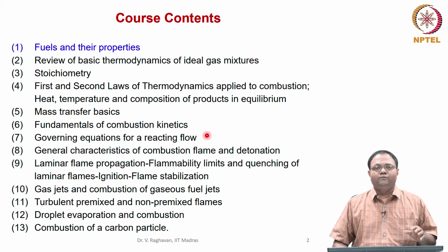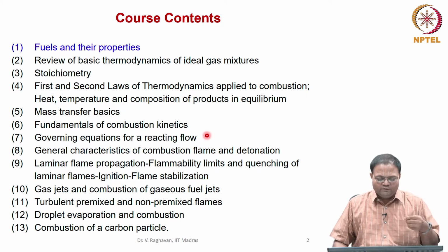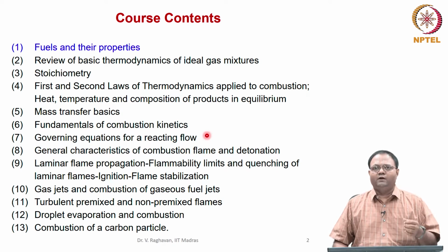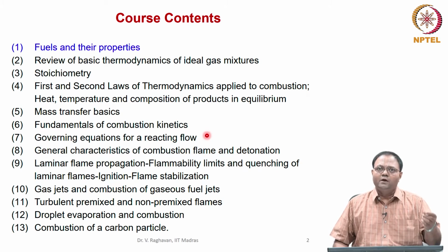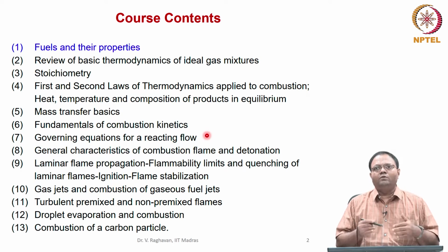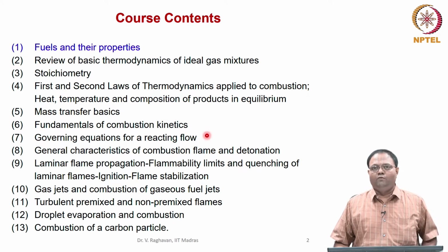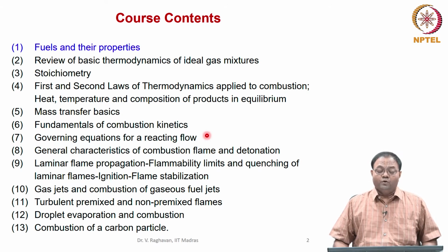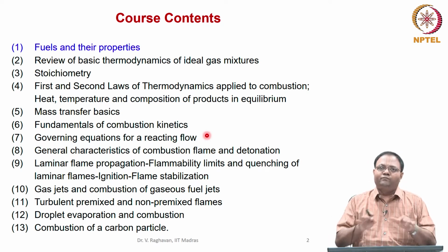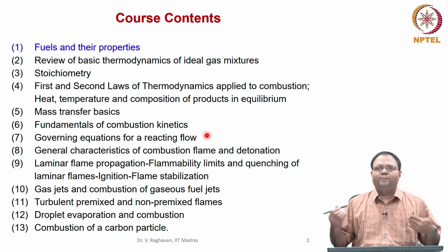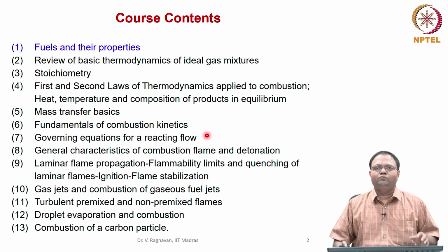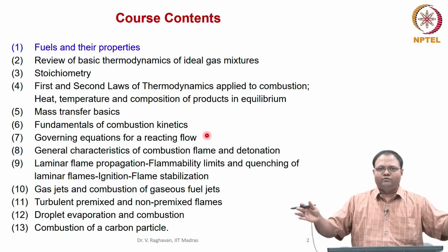For example, if there is a combustion taking place and a flame zone is formed, when I say reactants, I mean fuel and oxidizer. When the reactants are supplied to the combustion zone, before reaching that zone, if they are mixed, then this is obviously called a premixed mode of combustion. Now when they are separately fed to the combustion chamber and they mix only at the flame zone, then we get non-premixed. So these are the two extreme modes of combustion.